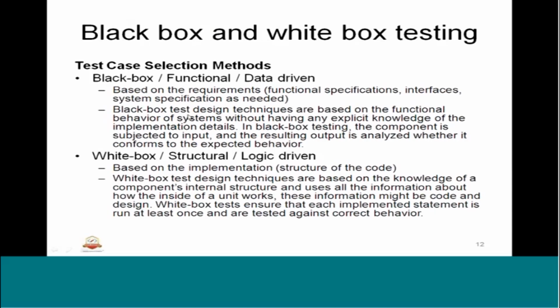Black box test design techniques are based on the functional behavior of systems without having any explicit knowledge of the implementation. As I said in earlier sessions, the user or the test designer will not have any knowledge about the internal details. He knows the box, that is the embedded system, what it is supposed to do, what the specification is, how it can be fed with real inputs, and what output he can expect. So in black box testing, the component is subject to input and the resulting output is analyzed to see whether it conforms to the expected results of the behavior.